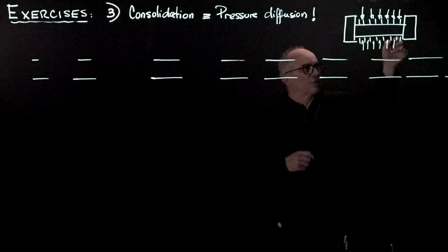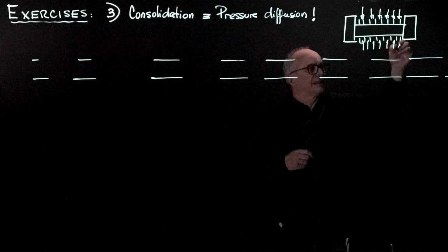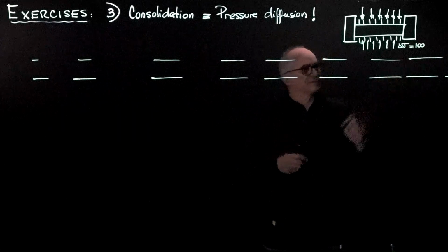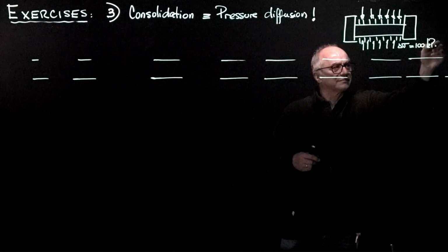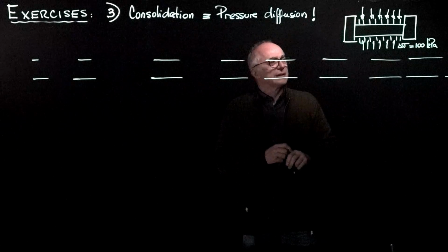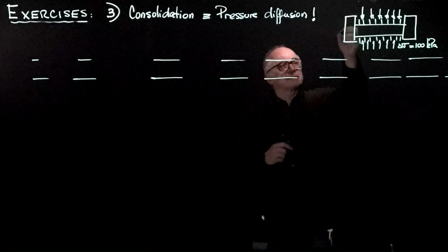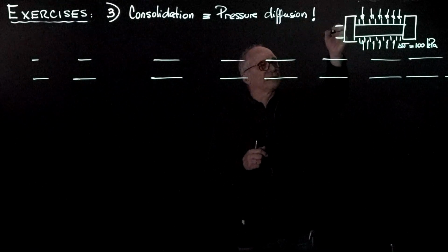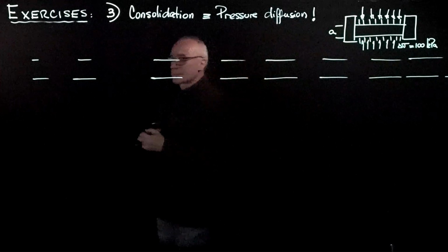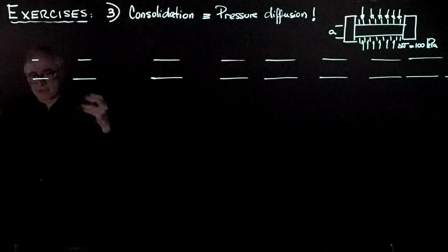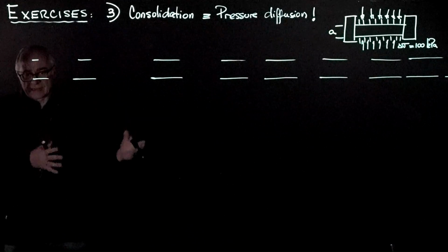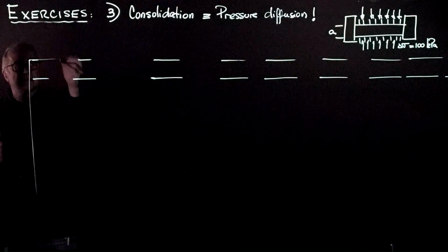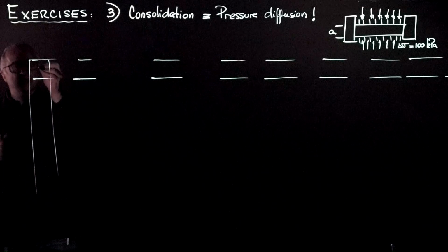And we can have values. For example, this delta sigma, we can say that is a value of 100 kPa, a significant stress change. And the specimen height at this point, we can say that it was height A. So the first column in our calculation, whether it is in an Excel or in any algorithm, would be to place a height of the specimen, so the coordinate z.